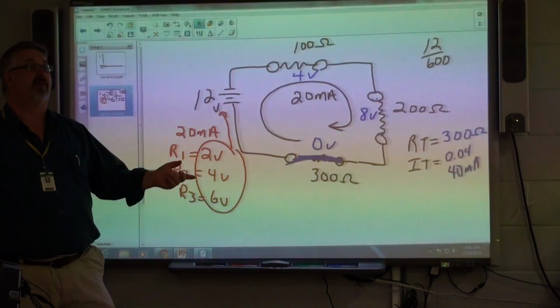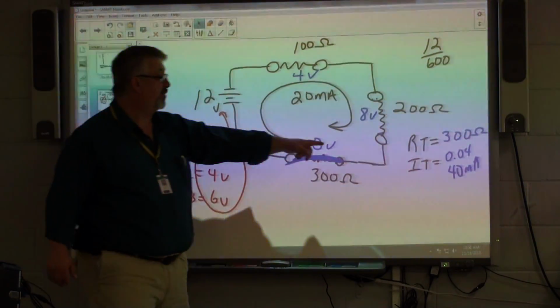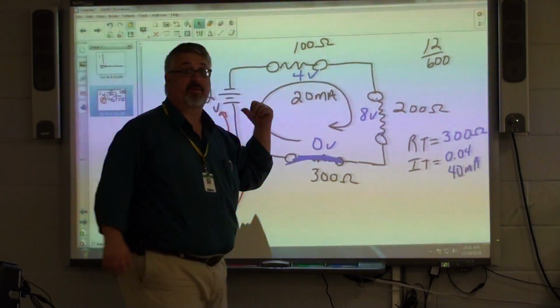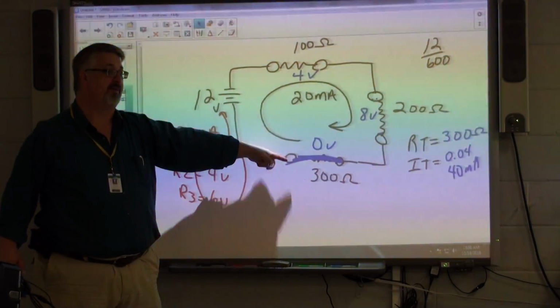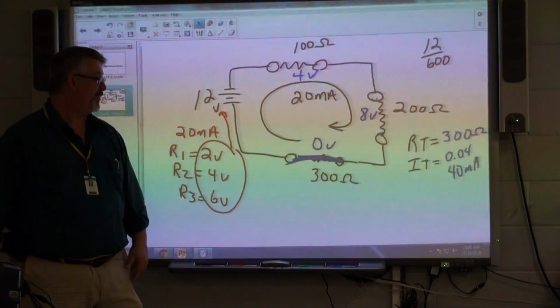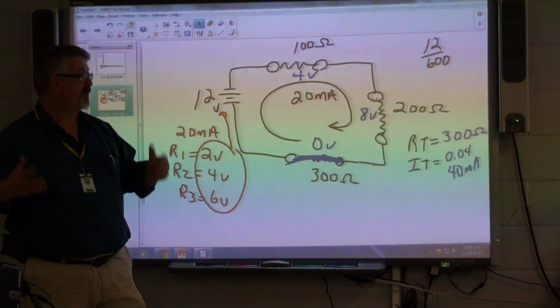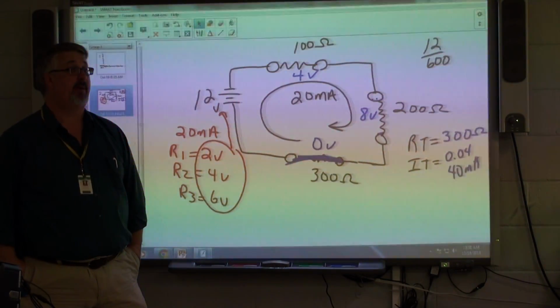So that would be indicative that something's going on that shouldn't be going on. Now our sum, 4 plus 8, still equals 12, but we're not dropping anything here. So if that's a glob on the back side of that board, we've got to turn it over and investigate. See what happens. So that's what can happen when we short a resistor, and it does happen.